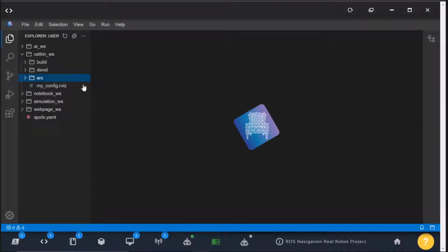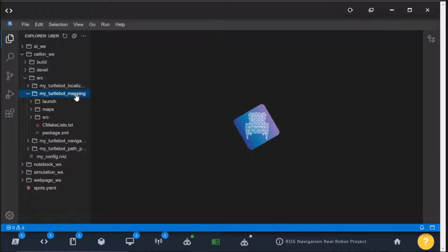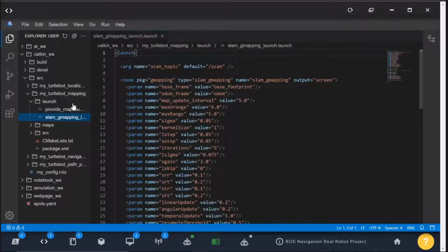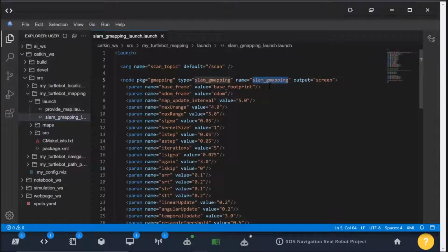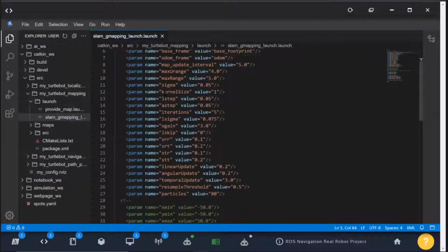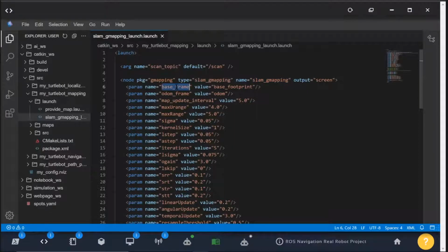Yes. Okay. The first part of the project was mapping, using gmapping. As you can see, this is a SLAM gmapping node launch file that runs the slam_gmapping node of ROS. We have different parameters here, such as the scan topic, the base frame of the robot, the odom frame name, and different settings relating to the laser range. After we run this launch file and move the robot around the environment, the map becomes complete, and we can save the map with the map_saver package.